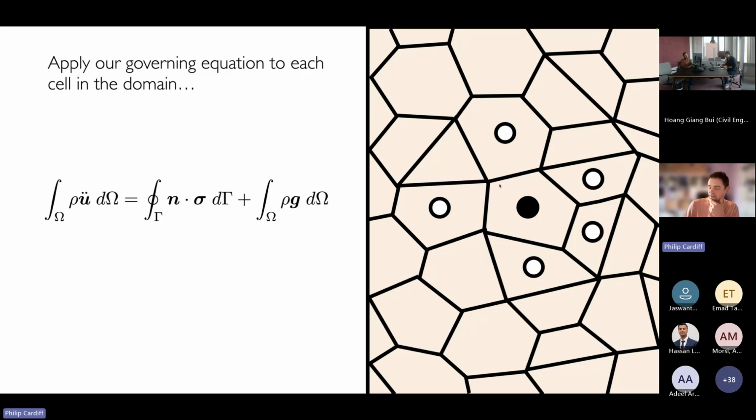And then you apply it to each control volume or cell in your mesh. Immediately one thing that stands out is the finite volume method is normally derived for general polyhedral cells, or convex polyhedra. So you don't have to derive a separate stiffness matrix for squares or triangles; you just apply it to general polyhedra.